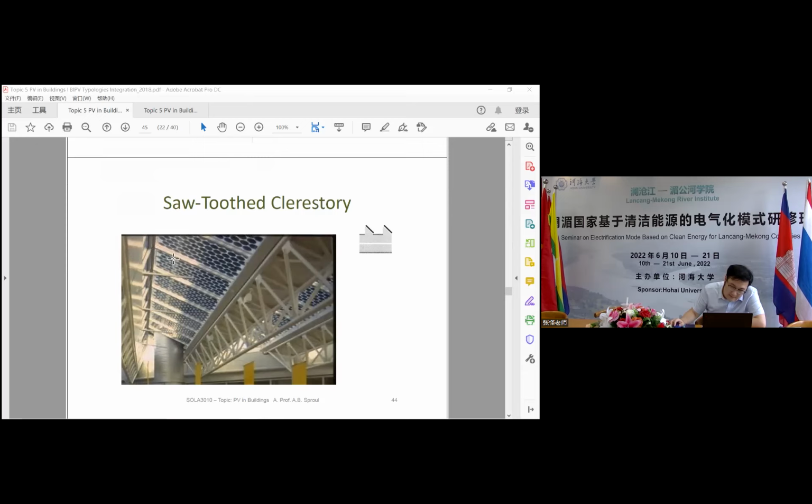On the front surface, we see PV modules with holes punched in them, or sometimes we adjust the array allocation of the PV solar cells so that there are some punched holes to allow light to penetrate for daylighting. So the back surface and front surface provide daylighting, and the front surface provides PV power generation in the sawtooth roof power system.